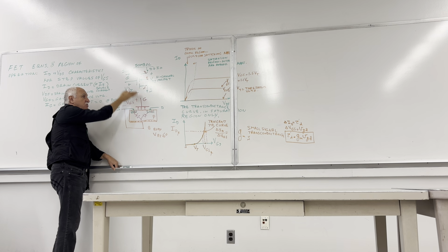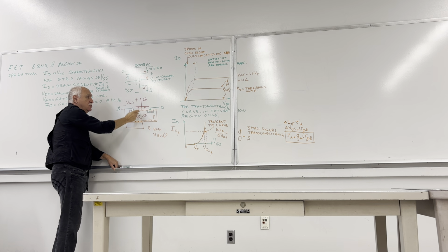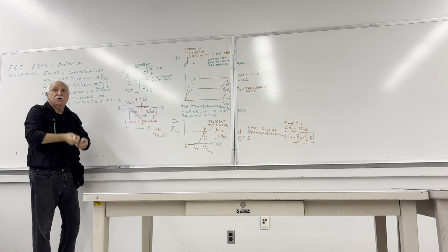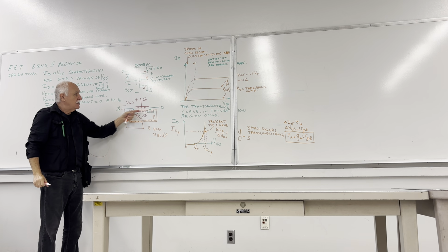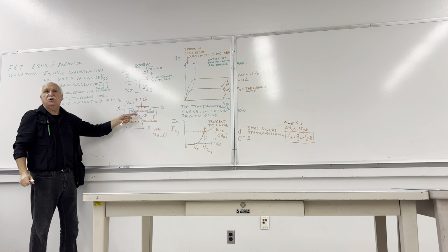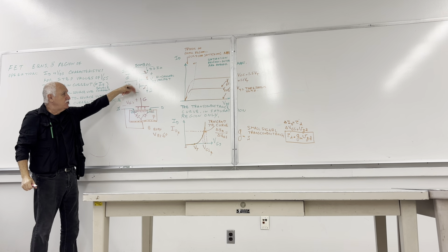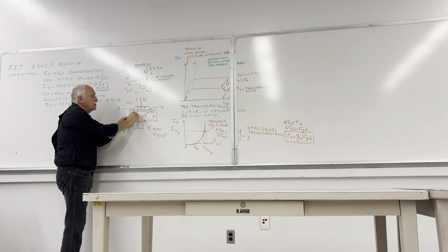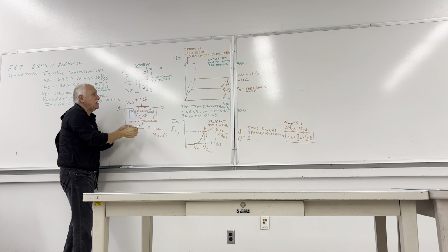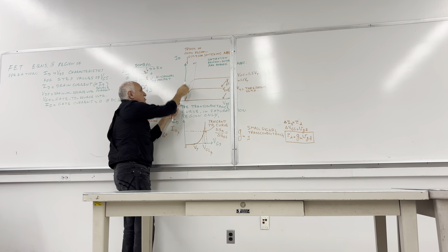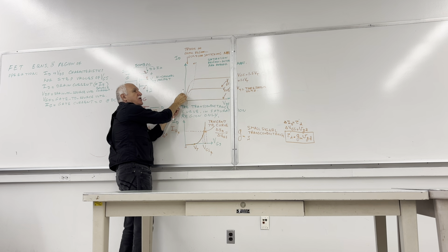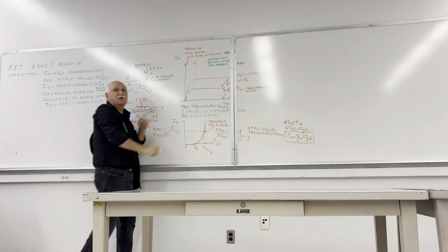So the electric force in the gate to the body will encourage the electrons to come to the front and align themselves homogeneously in that region. And the more gate voltage you put in there, the thicker and thicker this layer gets. Thicker and thicker, more electrons are building. That's why the more gate to source voltage you put, this resistance gets smaller and smaller. Conductivity gets better and better.